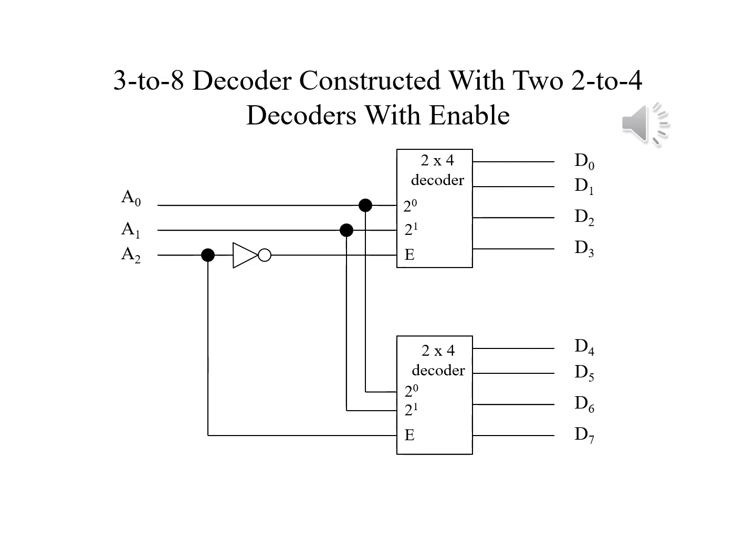The upper one gets, again, A2, gets the 1 for A1 and the 0 for A0, but it gets 0 for the enable. What it reads is that this is not enabled, and all 4 of the outputs on the second decoder will be 0.